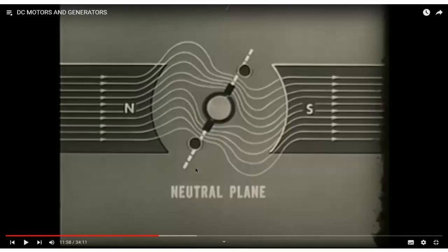If there is a severe armature reaction, you should move the brushes much further. If there is a small armature current, there's a small armature reaction, so the position change will be smaller. The change must be adaptive with respect to armature reaction, and it is difficult to maintain.